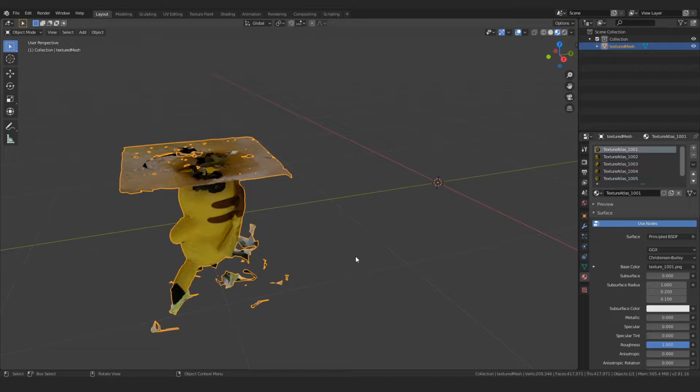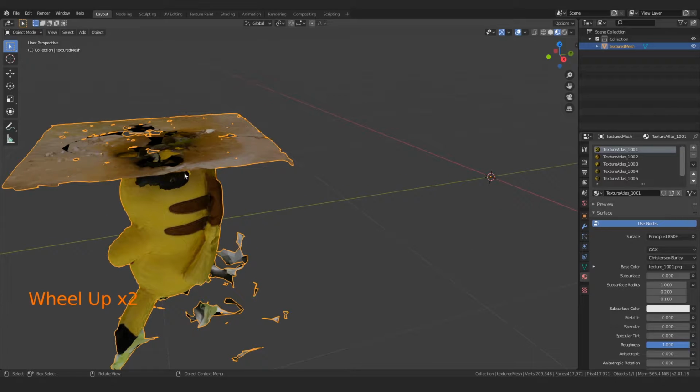If you take this Blender file and you move it to another computer, or if you move those image files out of the folder and you place them somewhere else and you try to open this back up again, what's going to happen is this is going to turn bright hot pink, and it's going to say there's supposed to be image textures associated with this file, but I don't know where they are. They've been moved to a different location, or I can't find them on this computer.